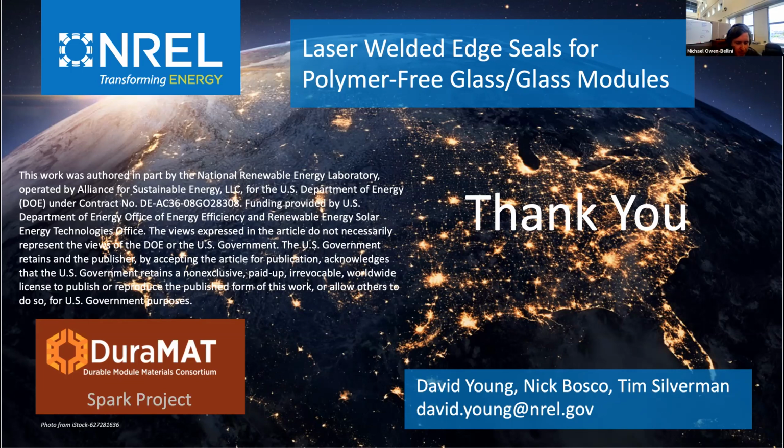David, is there a fundamental reason why NICE modules aren't widely used right now? I don't know if there's a fundamental reason. My personal opinion is that they tried to do too many things all at once. They used air pressure to keep the module together. And they also used that same pressure to press the metal onto the cells. To me, that's an awful lot to ask about pressure.